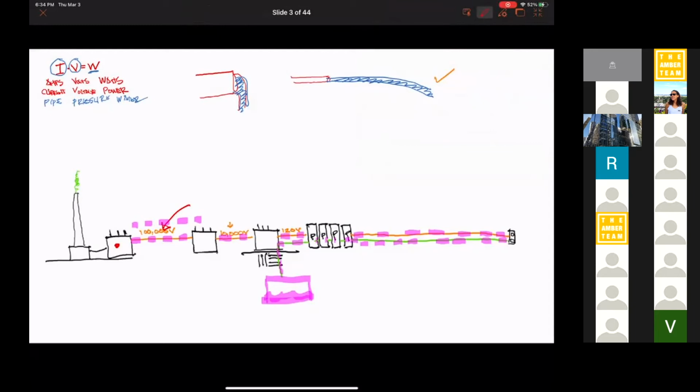Yeah, first of all, we need way too big wires, right? Because the pipes would have to be bigger to get the same amount of power to your neighborhood, to your region, to your state. We would need such big pipes that the wires would have diameters the size of a small grocery store hanging between the wires. So that doesn't make any sense. We can't have that. But the other reason is because we lose power along the way when we send it long distances at lower voltages, and it heats up. It gets really hot.